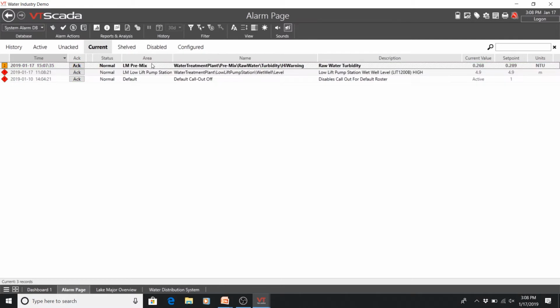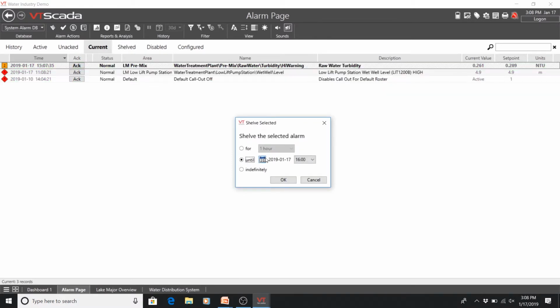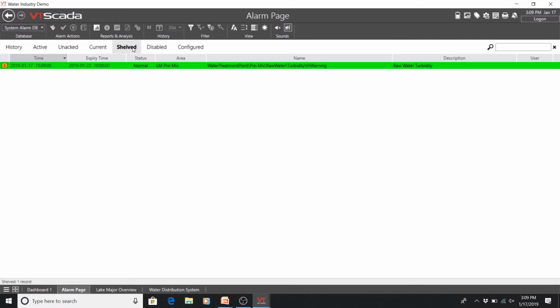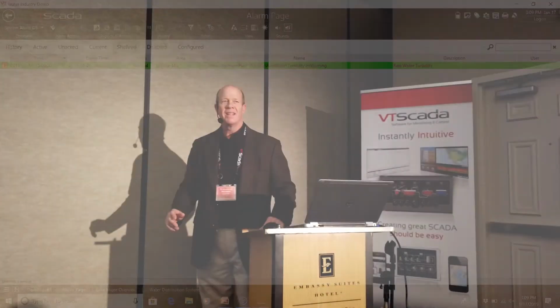So he's going to right-click on this and say, let's shelve this guy until, let's go pick the date of next Tuesday, the 22nd, until, say, 10 a.m. I press OK. Guess what? We now have that alarm shelved until Tuesday morning at 10 a.m.